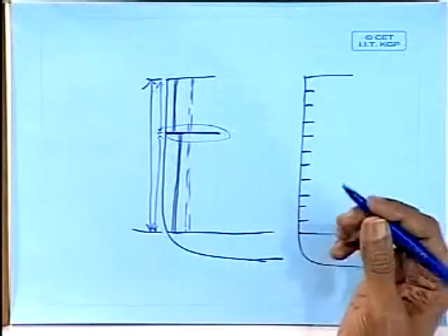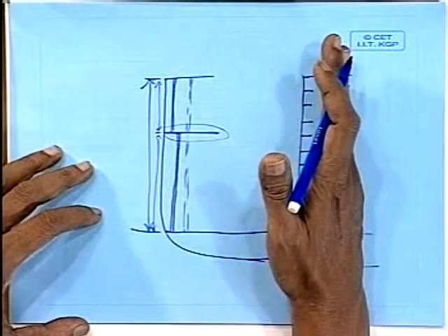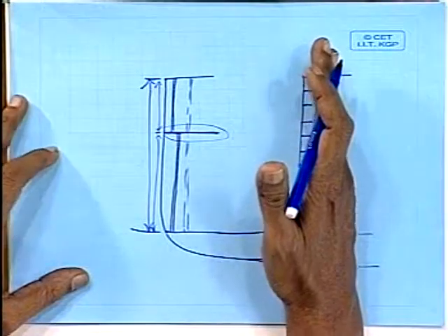What gives the transverse strength? That is strength against torsion, particularly the twisting stresses that are developed. What gives the strength if I do not have a transverse member? So that I have to also do. So after doing this, at every regular interval, maybe third or fourth frame, we give transverse stiffening to these longitudinals. But the longitudinals are more primary than transverse in this case.